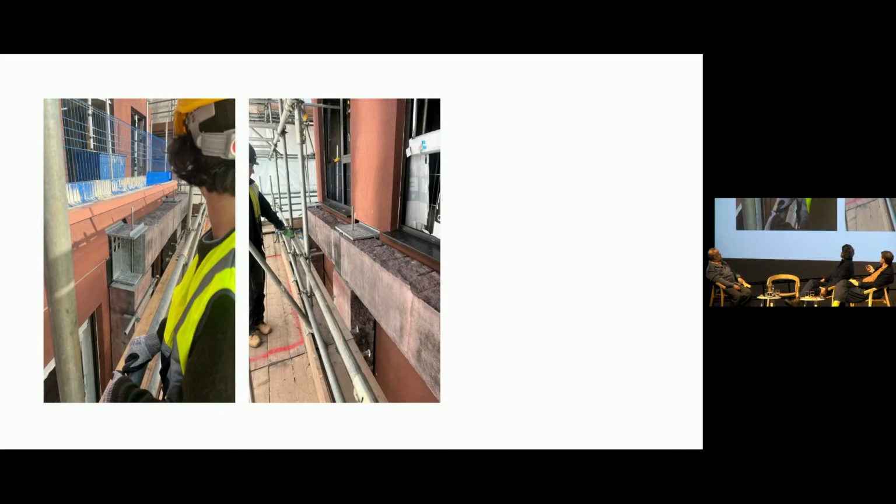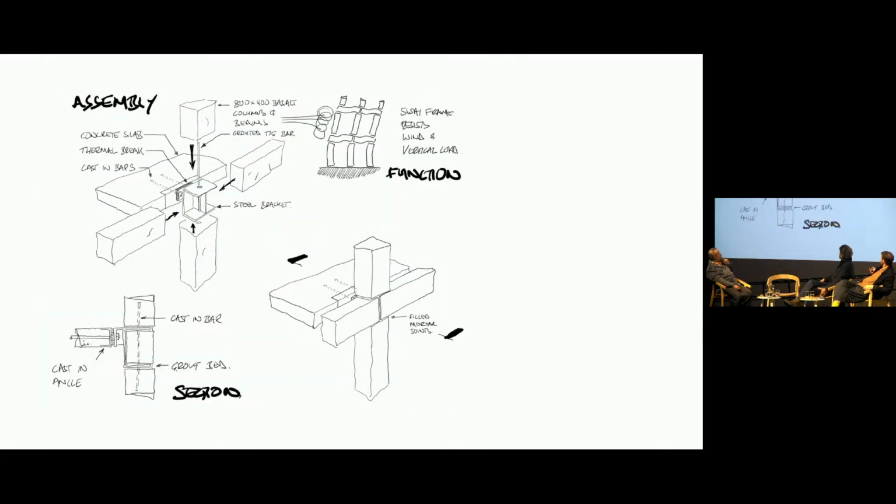The key to the building is the way that the stones are connected together. So the moment connection between the beams and the columns, connecting columns with the beams in a cast-in way, cross connections is very important. So there's a steel bracket, firmly bolted from the concrete slabs on the inside. The stones wedge in on either side, and they're tied vertically through there by a tie.